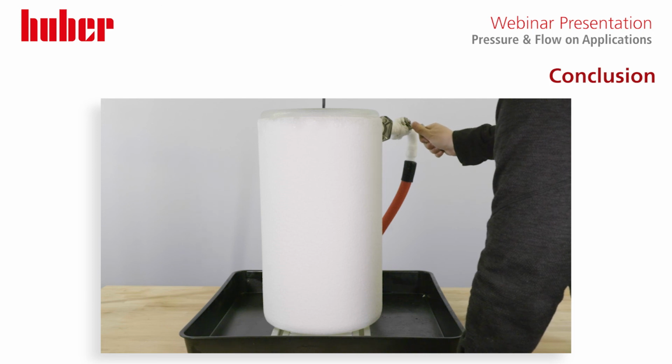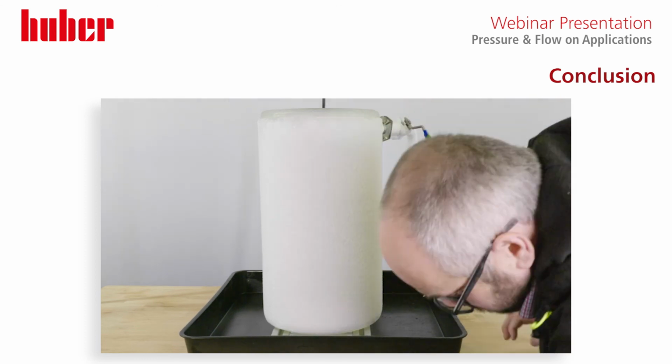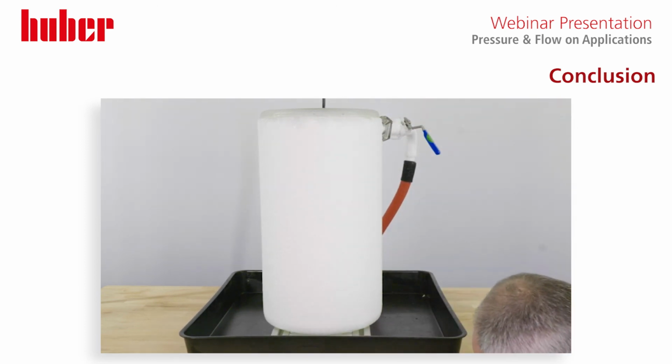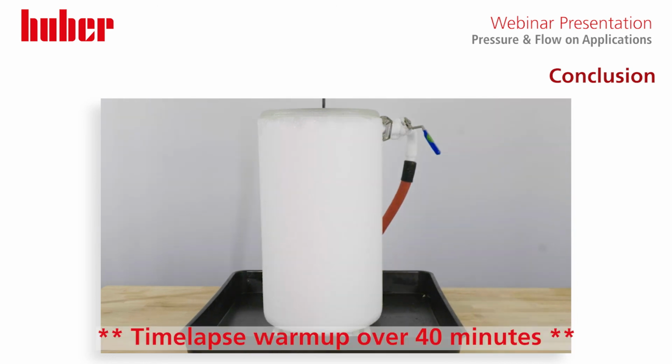We didn't have a live unit on this. We've isolated it from the unit with shut-off valves. There's nothing pumping. This is purely and simply oil expanding when it's getting warmer. Like I said, it only increased by 90 milliliters, but that 90 milliliters locked in this glass vessel was enough to apply 5.4 bar of hydraulic pressure.